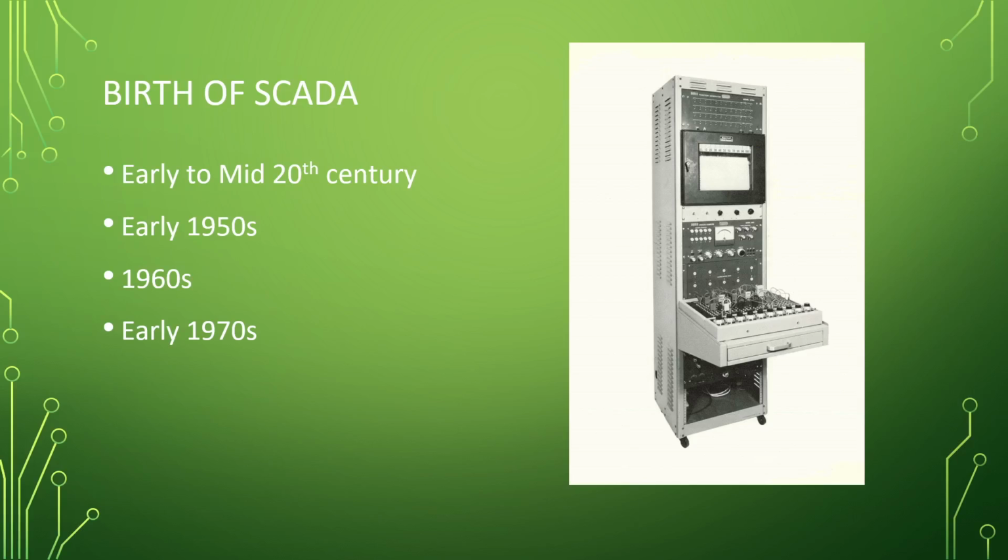And again, like an actual control cabinet, they might all be white because of the wire they used. Now, hopefully they numbered them. So you would be able to go, oh, this is wire number 2, and then you could go find wire 2 that should connect to this relay. You go, there's wire 2, hopefully. Not necessarily. But when something changed in your process, it's like, okay, we need to make this happen for longer or turn the conveyor off sooner or whatever the case was. Now you had to physically unwire things, wire stuff back together, and again, hope you got it right. So they were a pain to reconfigure, a pain for finding faults, and they took up lots of space.